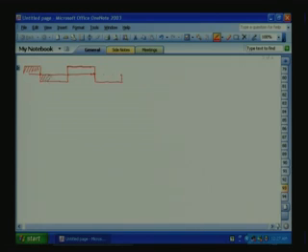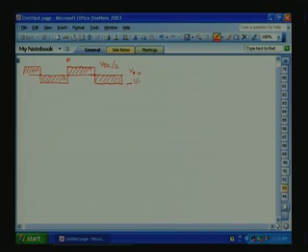This is our Va0 pole voltage. Let us say our omega t starts from here. This is Va0, Vdc by 2 and minus Vdc by 2, and Vb0 pole voltage will be 120 degree phase shifted.